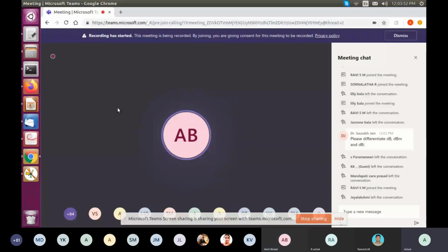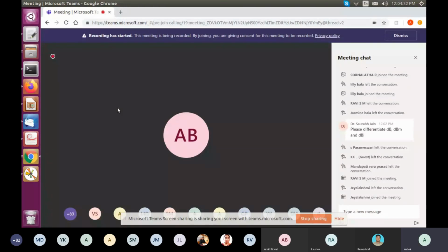I think Dr. Saurabh Jain has a question. He was asking to differentiate between dB, dBm, and dBi. So quickly, dB is a measure of loss or gain. dBm is the unit of power. When you talk about dBm, you're basically talking about milliwatts in linear scale getting converted into dBm in log scale. And when you're talking about dBi, you're talking about, once again, a dimensionless quantity, but with respect to an isotropic antenna. And that is what dBi is.